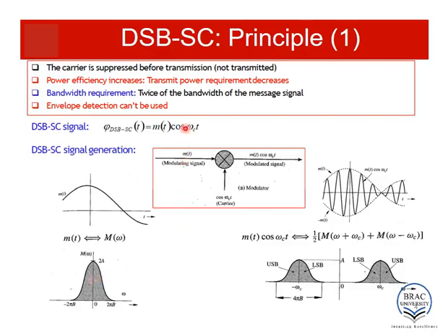The carrier frequency is omega_c. So in the omega domain, this spectrum will be shifted to omega_c central frequency and minus omega_c central frequency. And as you can remember, the amplitude will now be half of the original amplitude. In this case, the amplitude was 2A, and in the modulated signal, the amplitude of each of these spectra is A.